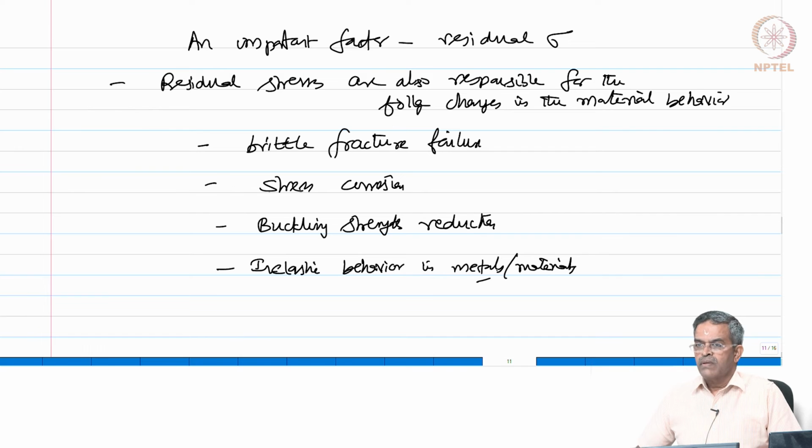But you know friends, residual stresses development cannot be avoided. Okay. It is an inherent part of manufacturing and fabrication process, because when you start building the connections, there is always a high probability that it will land up in development of residual stresses. So, this will now start prompting a low yield stress, which will govern the design. So, elastic design of structures controls the design till this point, therefore, it is not considered to be a good method of design. Therefore, friends, designers shifted the design procedure from elastic to ultimate load design.